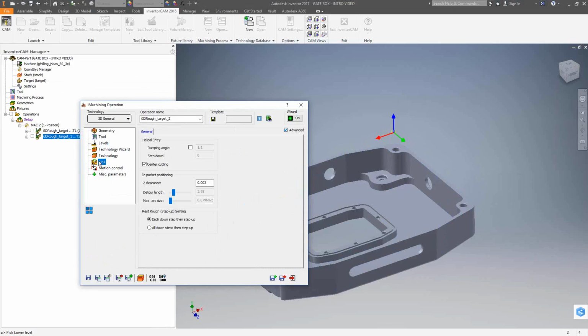Now, under Link, I skipped it over just because it really just applies to the overall use of iMachining. If you have a non-sensor cutting tool, so let's say it's a non-sensor cutting standard end mill, or an indexable or an insert tool, that affects the helical entry used by iMachining. So you'll want to uncheck this box and modify your step down of that helical entry to account for the fact that it's non-sensor cutting. Also, I didn't mention, but if you have any pre-drilled holes or any previous geometries or previous toolpaths before your 3D iMachining, it still recognizes those as well. So it always acts as a rest mill operation.